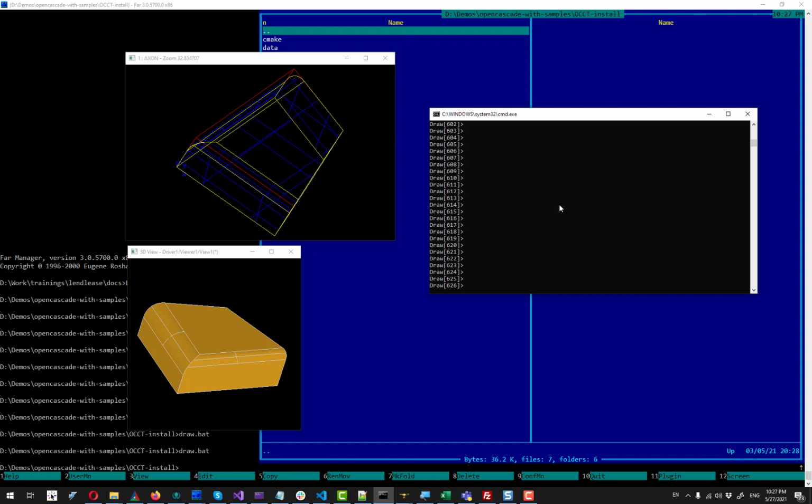So first thing to check is that my shape is sound and perfect. For that I'm going to run this checkshape command, and here I type this res. I'm also not quite sure right now what this res object is, so let me check it again. What is res? I can also point here and interactively select this object on a scene. And you see that res is a shape, it's a compound, and that's kind of surprising, because I would expect it's a solid object.